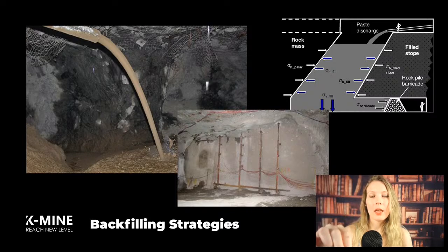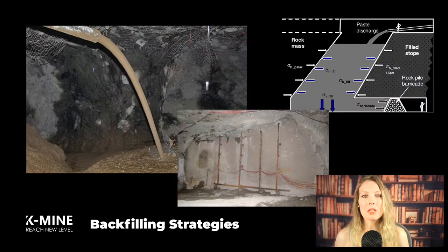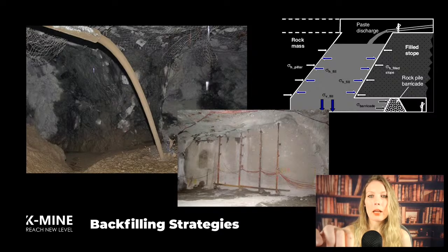A combined approach using geostatistical modeling, stability methods, and economic analysis is recommended for optimizing stope design. By using real-time data and updating geological and economic models, mines can adjust stope boundaries to improve extraction efficiency. This fits with the modern adaptive mine planning, where stope designs can change based on ore body conditions and operational needs. Overall, optimizing stope structural parameters requires a balance between geological stability and economic performance.